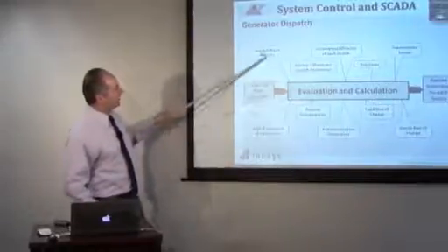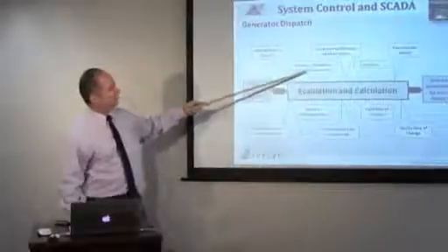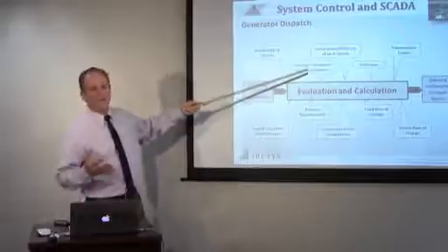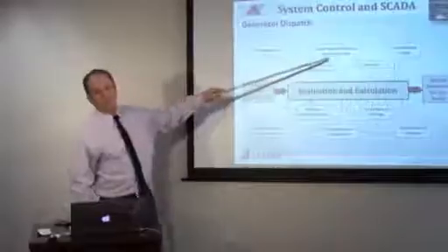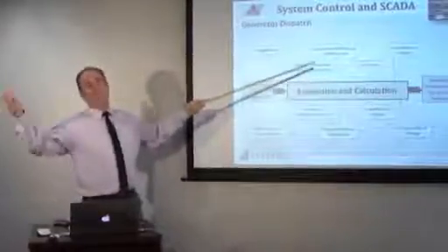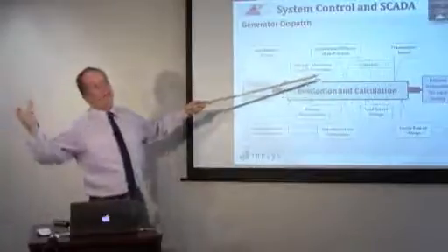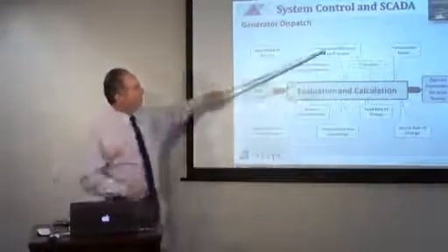It considers things like, well, what sources are available? What are the startup and shutdown and cost constraints? What if we have to start up a whole new generator just to do it? There's some cost involved with that. The incremental efficiency: for some units, the next 10 megawatts is like nothing extra. Some would be a lot extra. We've got to start up a whole new firing system or something. You've got to do something.